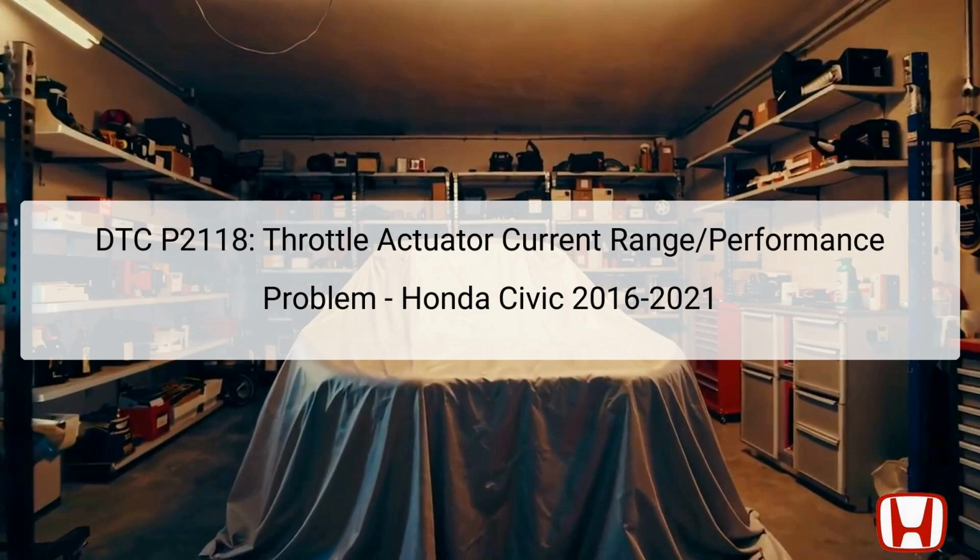The DTC P2118 signifies a throttle actuator current range performance problem in the Honda Civic models from 2016 to 2021. This error code indicates that the vehicle's powertrain control module, PCM, has detected that the current being provided to the throttle actuator is outside of expected thresholds.